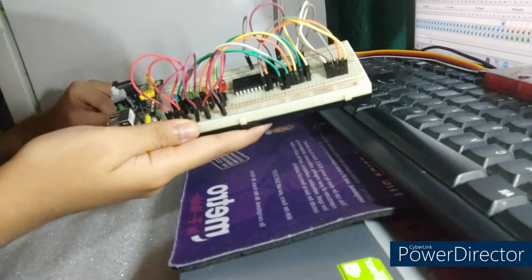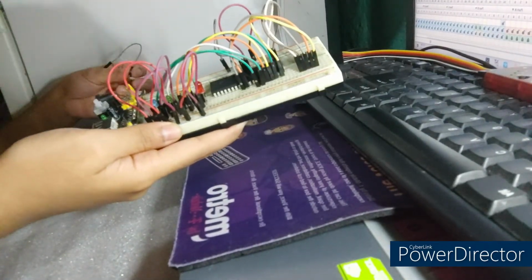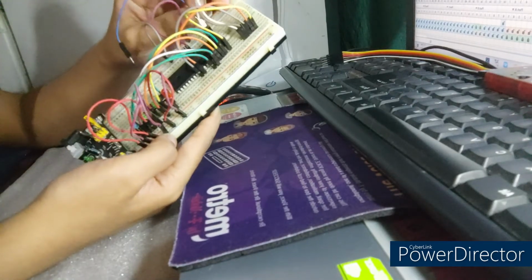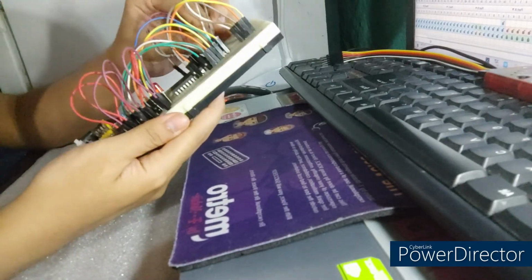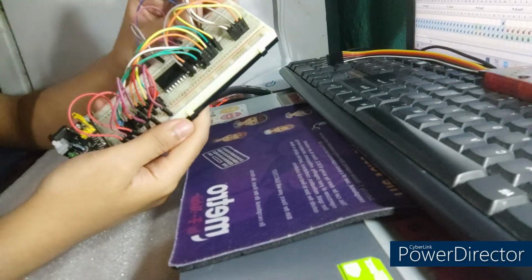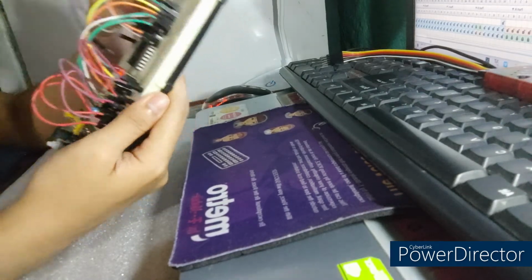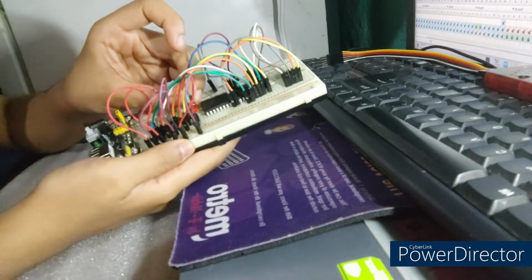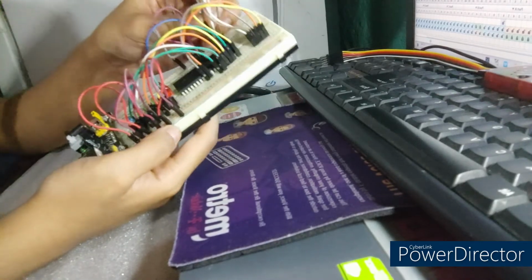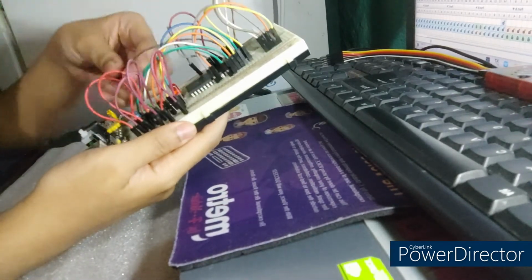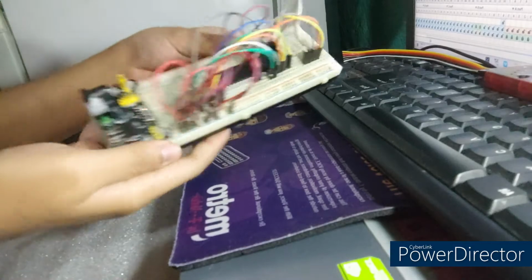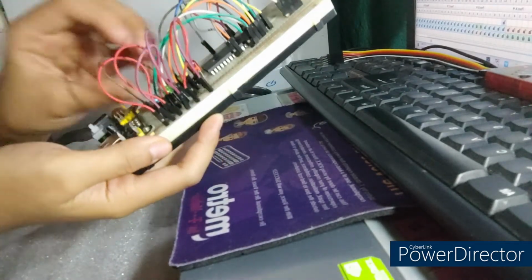So next one, our switch number 1 will be on RB4 or pin 37 of our IC. So 40, 39, 38, 37. So this will be our switch number 1, pin 37, connected to our switch number 1 here. And then our switch number 2 will be on pin number 36, so connected here on our tactile switch. Then let's ground both of our tactile switches here.